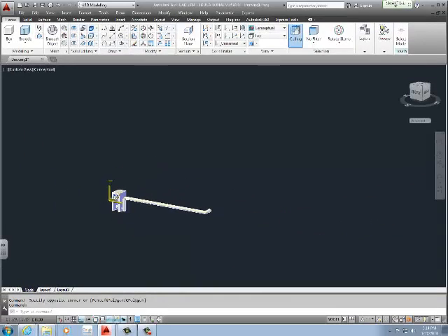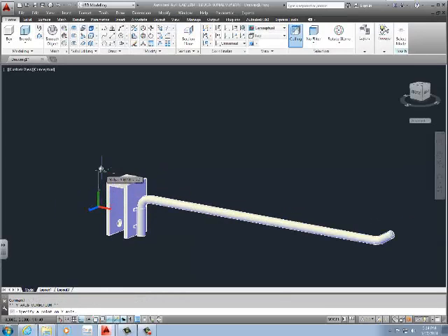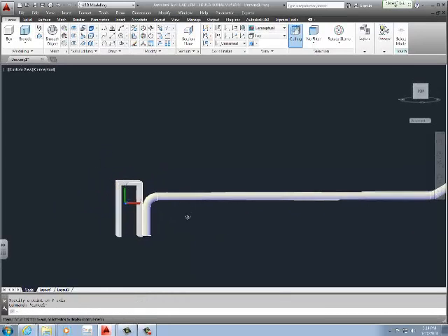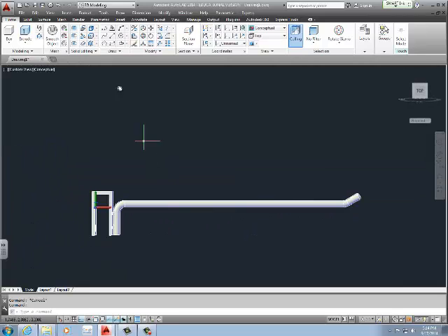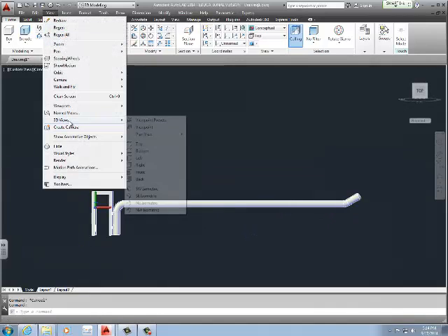So I'm going to rotate my UCS so I see X and Y. Critical, so keep in mind, you look at it like that, okay, and I'm going to go exactly to that view. I'm going to 3D views, and I'm going to go to 1 inch. I believe that is the top.